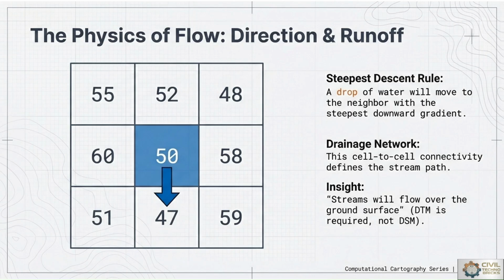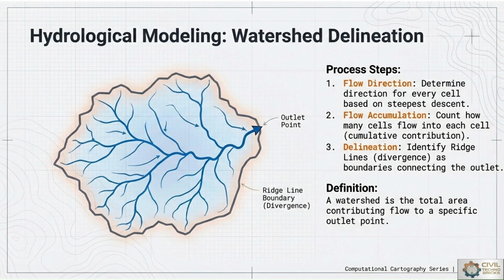This is the first step in automatically delineating a watershed, identifying the natural drainage paths that will inform the design and location of a culvert below a road surface, railway line, or bridge. For hydrological modeling, from the watershed delineation point of view, by calculating the flow direction for every pixel, we can determine the flow accumulation, a count of how many upstream pixels drain into a specific point.